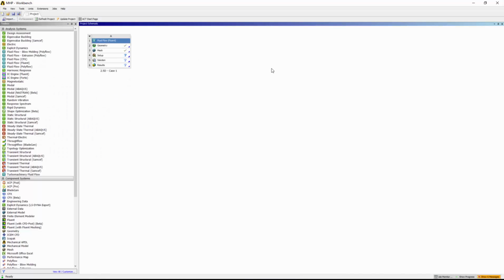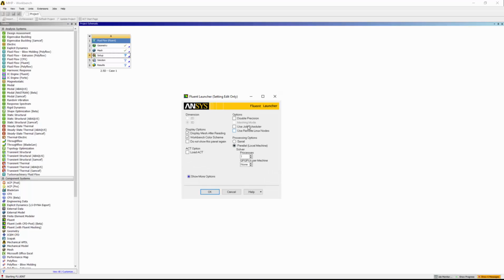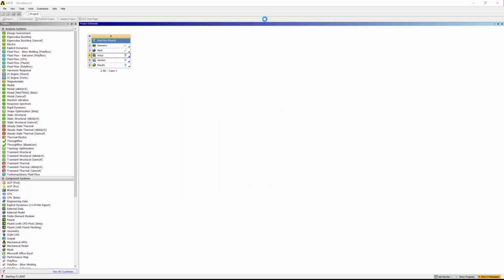When the Fluent dialog box appears, click on Double Precision and then increase the processor to one less core than you have. This computer has 4 cores and will be using 3 processors, where one is left for reading and writing on the disk.